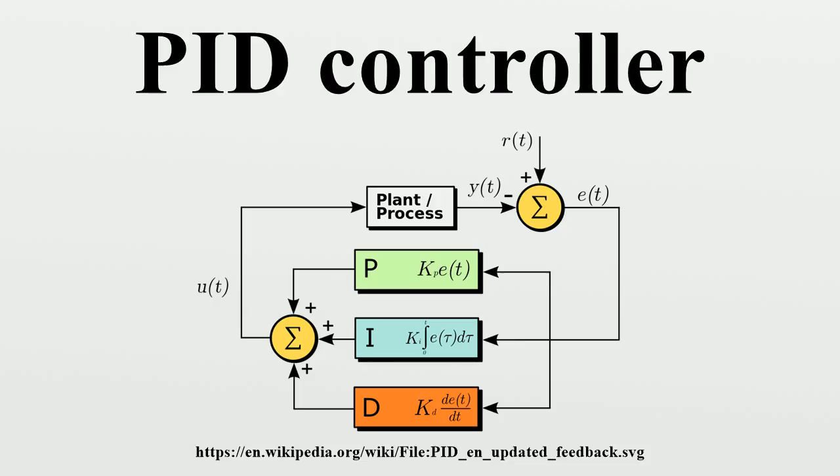A fast PID loop tuning usually overshoots slightly to reach the set point more quickly. However, some systems cannot accept overshoot, in which case an overdamped closed-loop system is required, which will require a P setting significantly less than half that of the P setting that was causing oscillation.